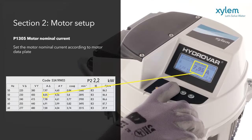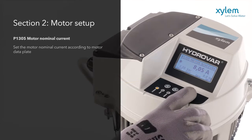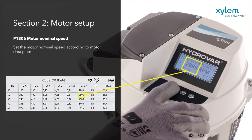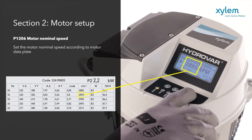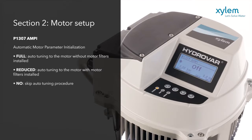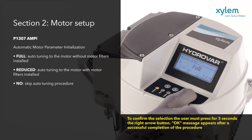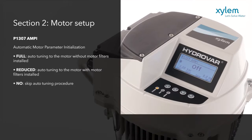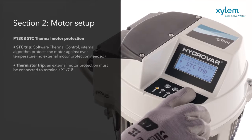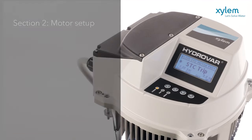If a generic motor is selected, the nominal current and nominal speed of the motor has to be set. Note that the Automatic Motor Parameter Identification process, AMPI, can take up to 3 minutes, during which time no other actions are possible. It's necessary to select the thermal protection settings for your motor, which will protect the unit from overheating. With the STC, Software Thermal Control, no motor PTCs are required as standard.